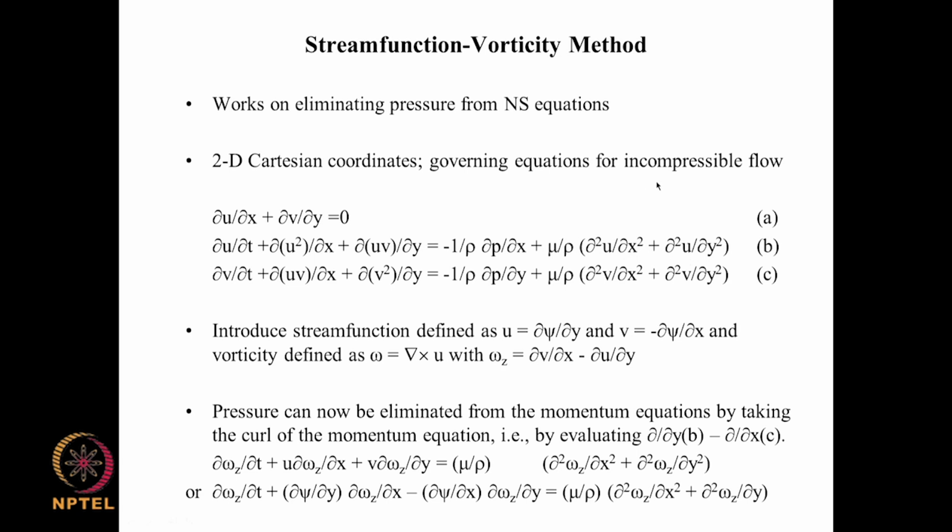Since we are looking at incompressible constant property flow, the second coefficient of viscosity term does not appear. It is usually something plus lambda times ∂u_k/∂x_k, and ∂u_k/∂x_k equal to 0 here. So the second coefficient term goes to 0, and this is the equation here. Since we are looking at constant property, constant density, gravity does not come into the picture. It has no way of influencing the velocity field, so we can subsume it in the pressure here, or we can simply neglect it.